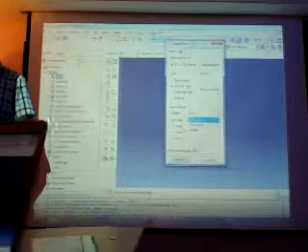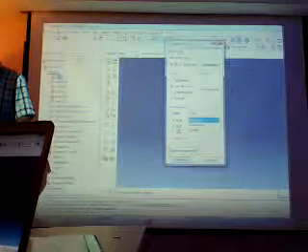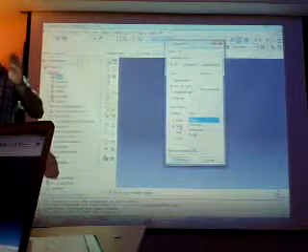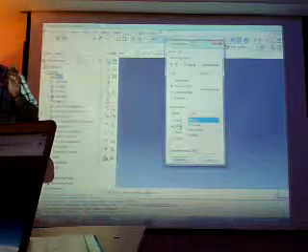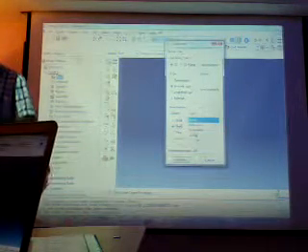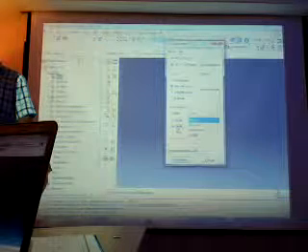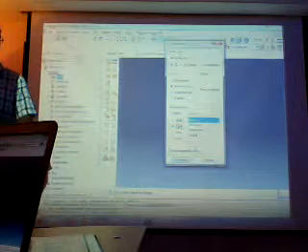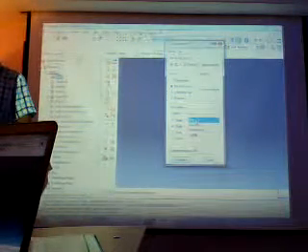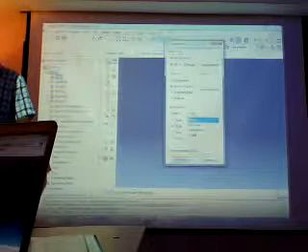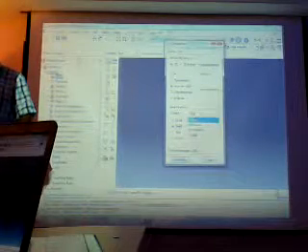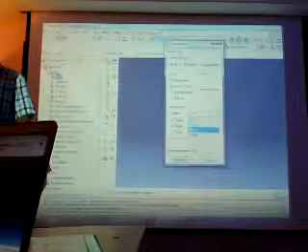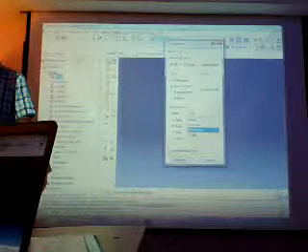Okay, die discrete rigid, and here I'm going to take shell. Why shell? Because in shell we can increase our mesh, our number of elements, and the computation time also decreases. So it will be a surface. So the die surface will be a shell. And the shape will depend on your designing ability. You can take any of them. Here for the die, I think revolution is easier than other types.